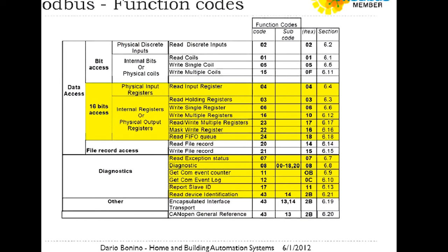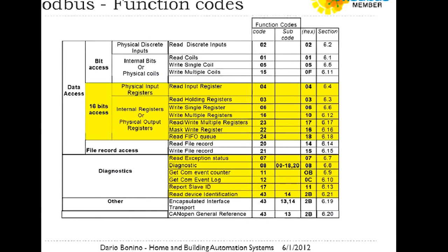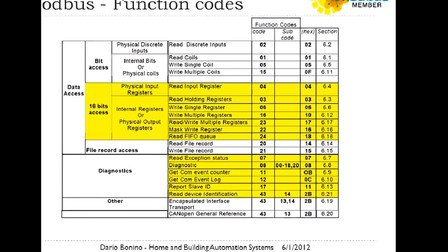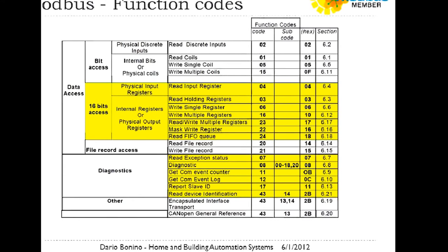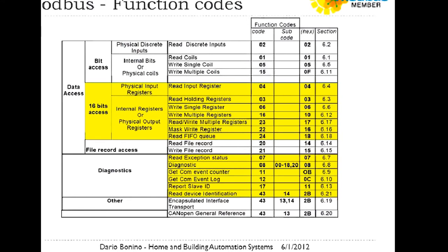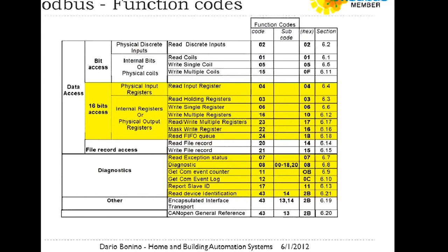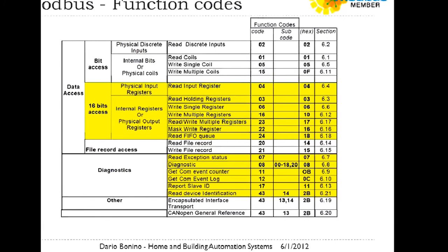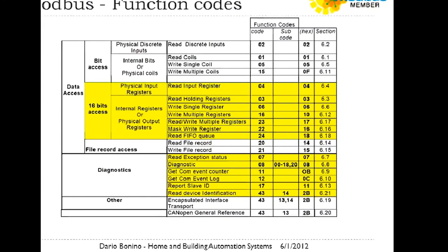So for example, the function code 01 means read coil. A coil is what you need to operate a contact on a relay. It's the electromagnetic part which attracts or not the relay contact. So if I want to read the coil, I want to read the state of the relay, 1 or 0, closed or open. And if I want to write the coil, I want to change the state. Okay? So something is starting to emerge. Here we read and write values instead of sending or receiving commands. And then there are many others, more complex.